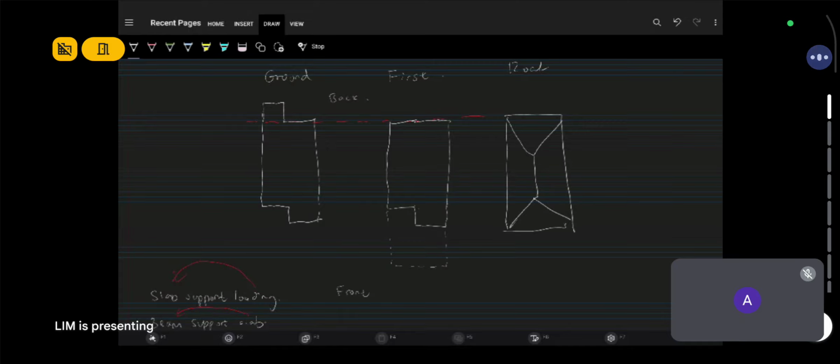Now when we frame up a building, we start from the highest floor. In this case, the roof. Because you already have a roof covering to carry the roof load, you don't need a slab. So you only need beams. The roof sits on the beam in this case.